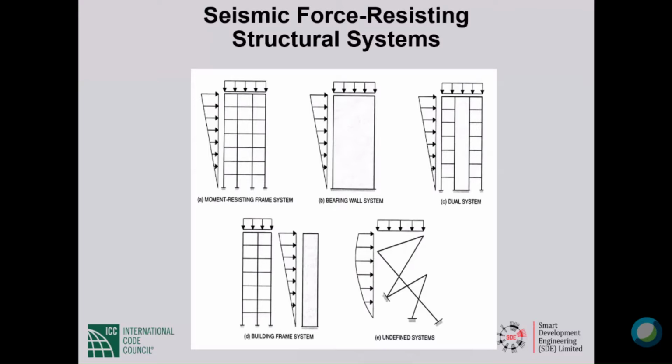In a shear wall frame system, we as engineers may not decide that the shear walls will carry 60% of the lateral loads and we will design the frames to carry the remaining 40% of the lateral loads. That is not our decision to make. The structure decides.